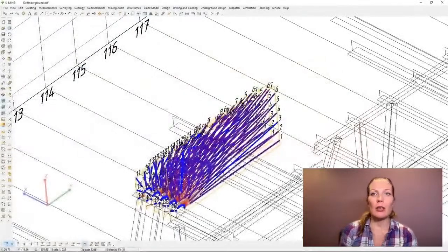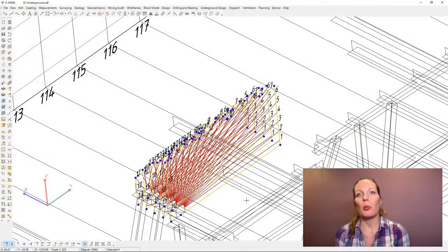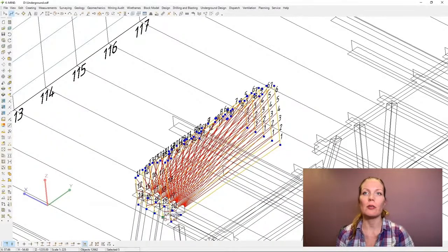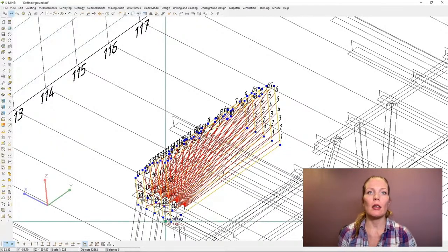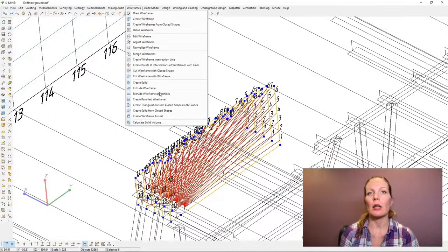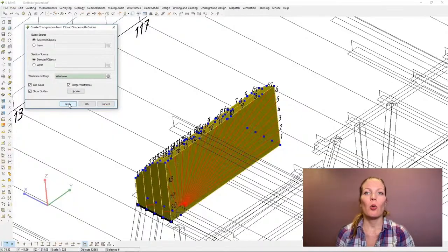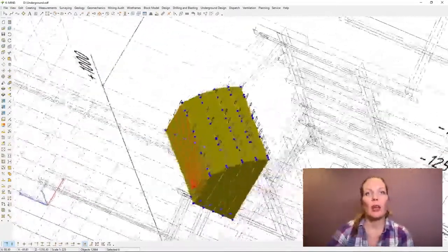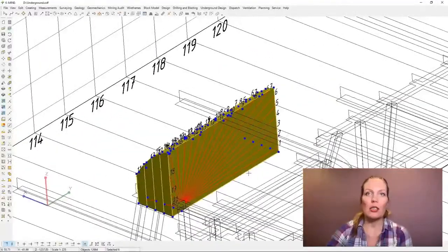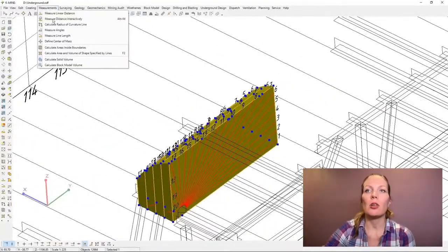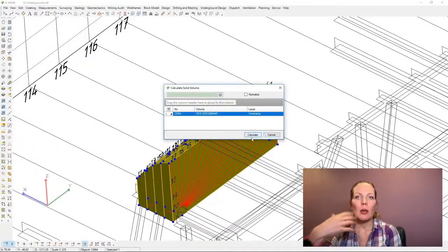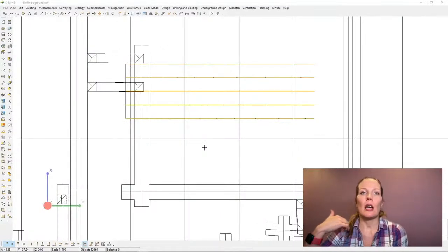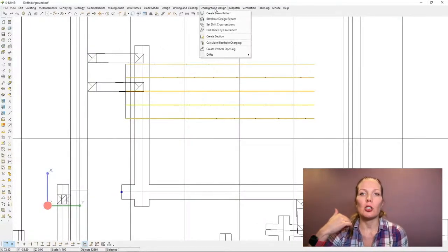In vein deposits mined by long hole or mechanized cut and fill, this usually means generating short axis drifts and drilling bays at the correct elevation and azimuth, while keeping the distance to the face minimal to preserve selectivity. In sturdy or gently dipping room and pillar layouts, integration is mostly alignment: snapping the optimized stope to the mine's existing grid, keeping pillars intact, and using established ventilation branches.